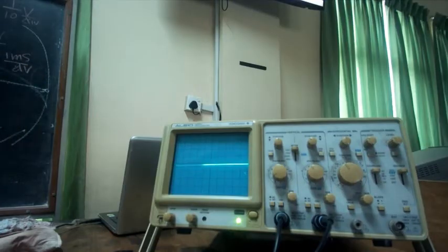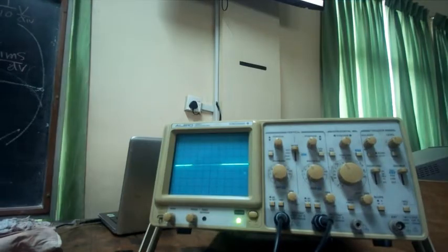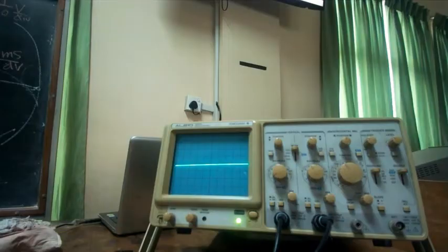If I have that, it will change at a rate where 1 division is 100 millivolts, so 100 millivolts per millisecond. This slope is 100 millivolts per millisecond. The whole thing is 1 volt, so it will take 10 milliseconds. So the slope is 1 volt per 10 milliseconds. You can figure out that slope, right?